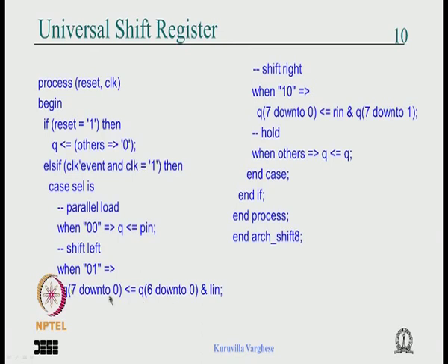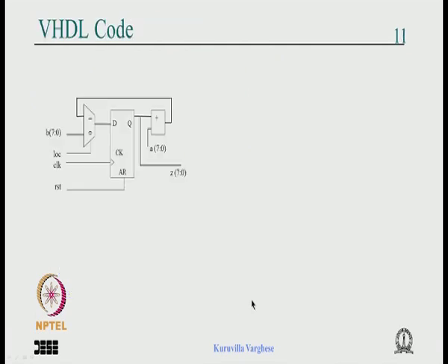Essentially it is the same. I am talking in terms of the hardware now, but in terms of the syntax in VHDL this is kind of a loop, and this is a vector assignment. Otherwise, circuit wise there is no difference. There could be a difference, because it all depends on how the synthesis tool infers the structure and how it is mapped to the underlying hardware. For us to try it out, maybe when we play with the tool we can take some example and have a look at how the synthesis tool handles the various types of coding.